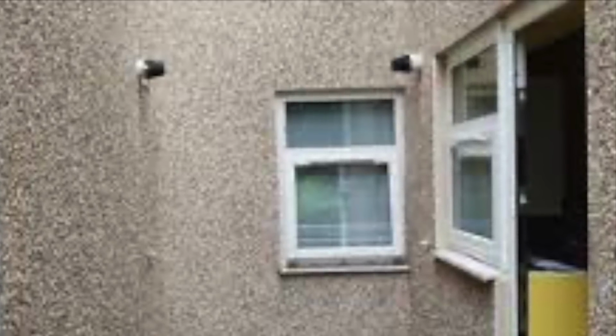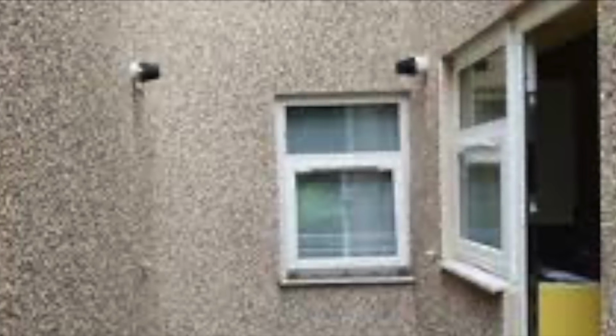So if you was going to install a new condensing boiler and the boiler on the left hand side is to be changed, then you can't put it there. You would have to go vertical. You couldn't even use a Plume Management Kit in this situation because you're actually over the boundary wall, unless the boundary wall is actually in between the wall and the window, which we don't know. So siting boilers like this are a big no-no.